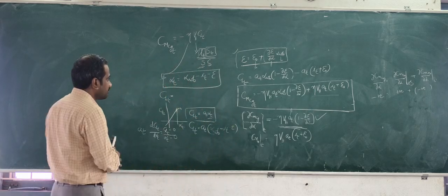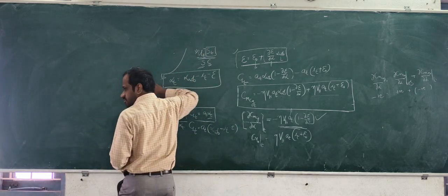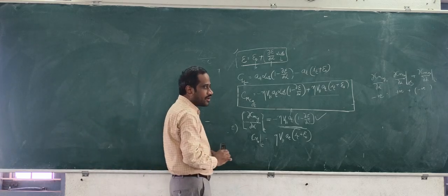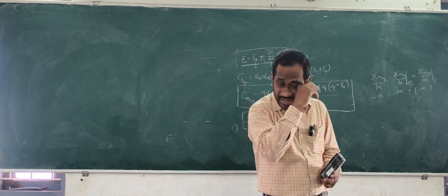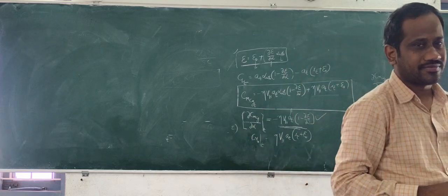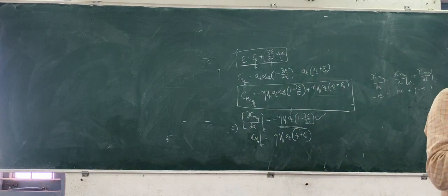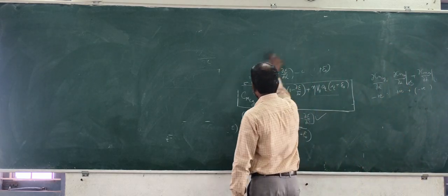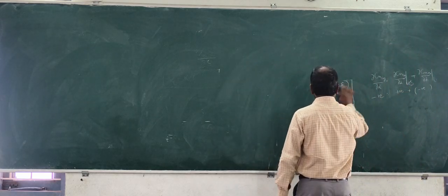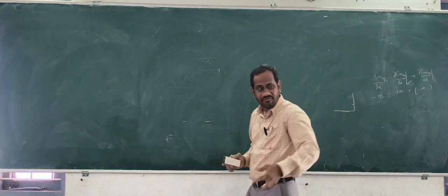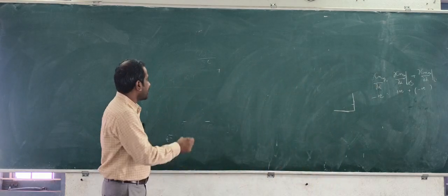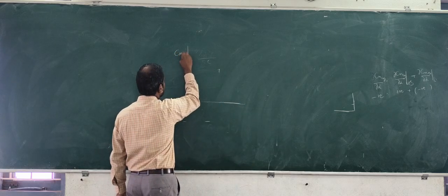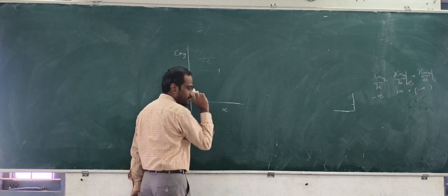I will clarify now. CM naught actually doesn't directly convey anything related to stability. Let's look at now. I will pose certain questions now. You please answer. Look at the criteria of longitudinal static stability. What is the criteria? It is the CMCG versus alpha of the whole aeroplane.